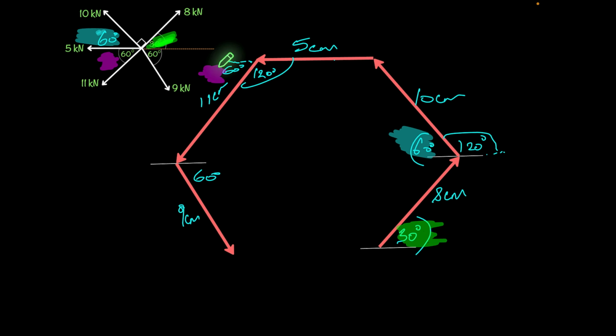So let's get the resultant force now. So this here will represent the resultant force at the bottom in green. And things to notice here is you will notice that all the forces on the diagram go around in the same direction. But as for the resultant force, it goes back onto those forces. So you'll notice that the tips of the arrows meet there with the resultant right there.